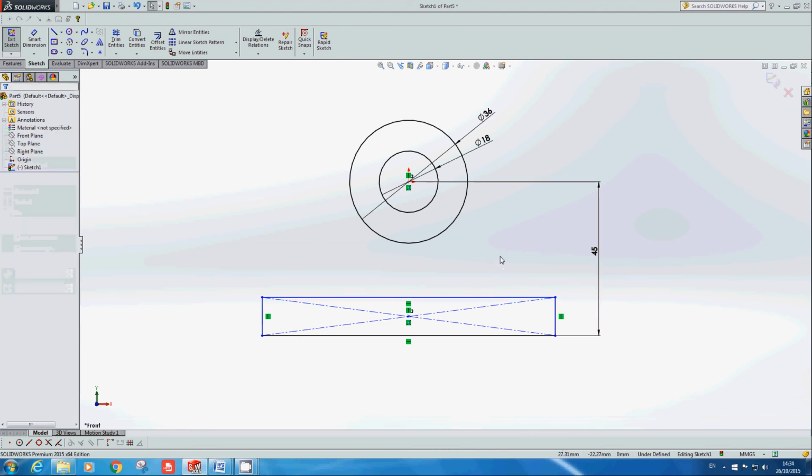A lot of the marks in the exam will be going for the weight, and if there are even slight discrepancies in the sketch, it'll throw off the weight. A lot of the time the reason is that the sketch isn't fully defined, or it's only been defined using fixed constraints. So again, fixed constraints, stay away from them.